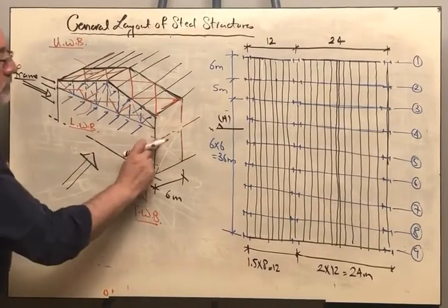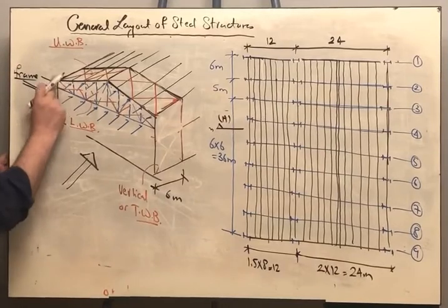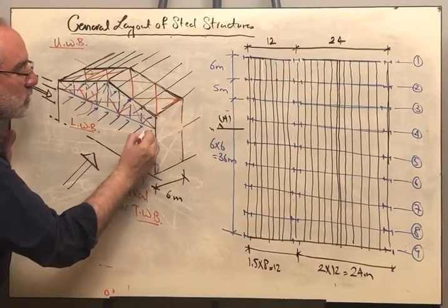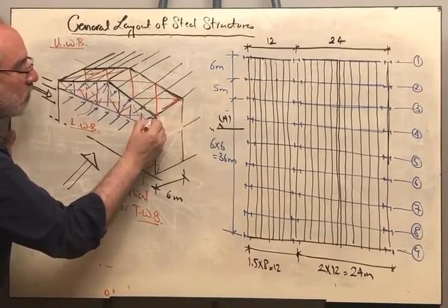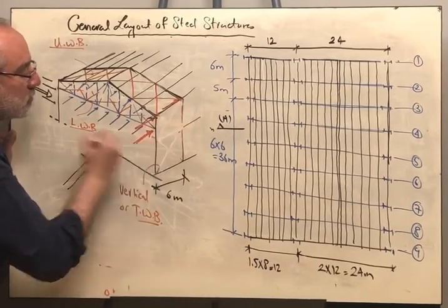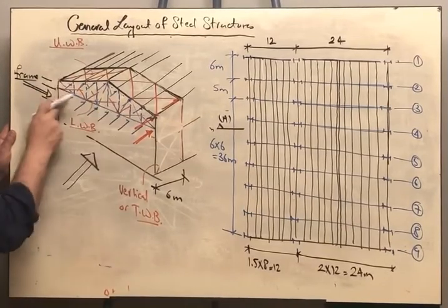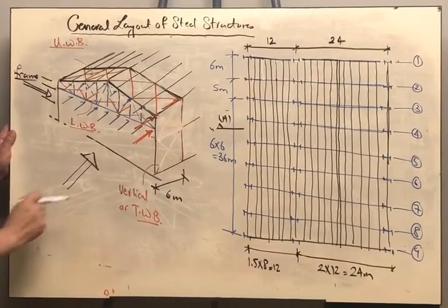Whenever you are having a truss like that and there is lower bracing, this means that the force is transferred to this column at this point and this point. Okay? Because these are the 2 points where the upper bracing and the lower bracing are attached to the column.